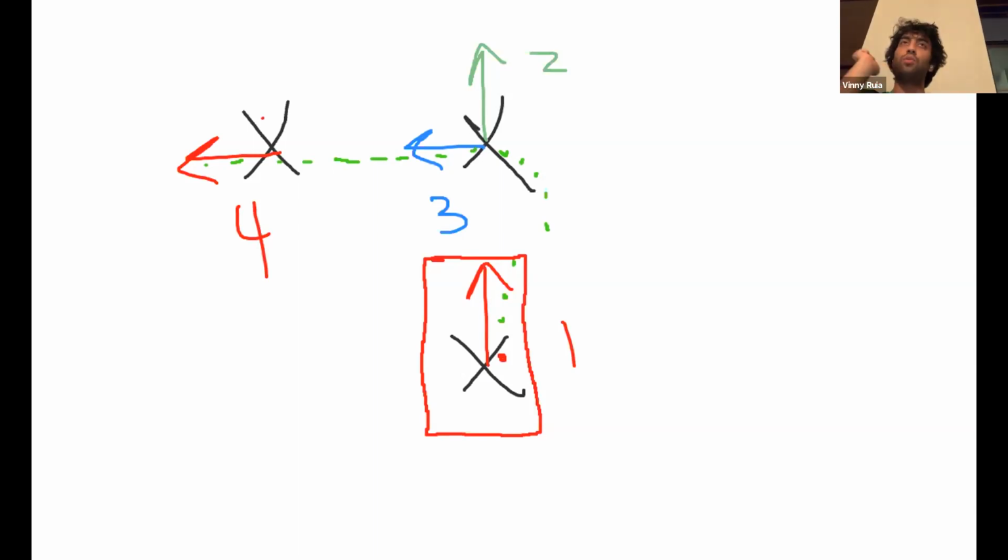Well, okay, so with move base flex, you can actually do that. You can give it a path that you've calculated yourself. And a path is a collection of poses, and poses have both position and orientation. So let's say you did record that green dotted line, you'd be able to feed that back into move base flex, and your robot will execute that directly, or as directly as possible. Right. Yeah.